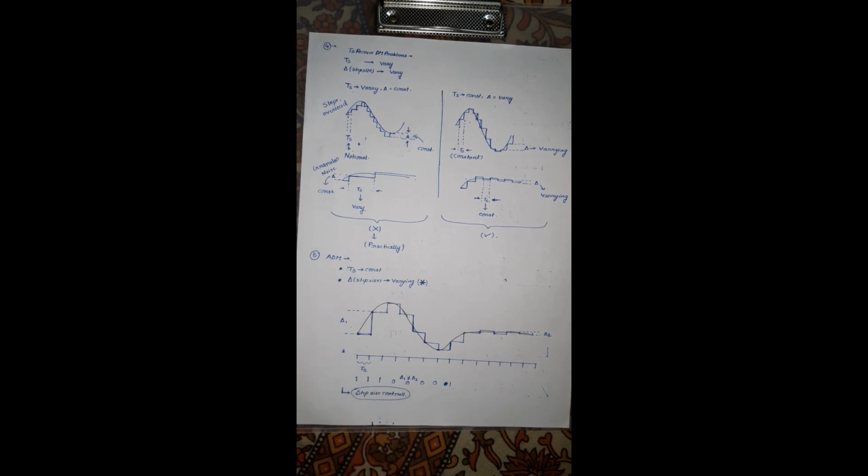Yes, for varying the step size, I have already told you there is a step size controller that I have already shown you. A step size controller is required. That means the DM and ADM block diagrams are almost the same. There is certain circuitry for controlling the step size. You can see that there is a step register, and this block has been introduced in ADM. The rest of the circuit is almost the same, and it is nothing but feedback.